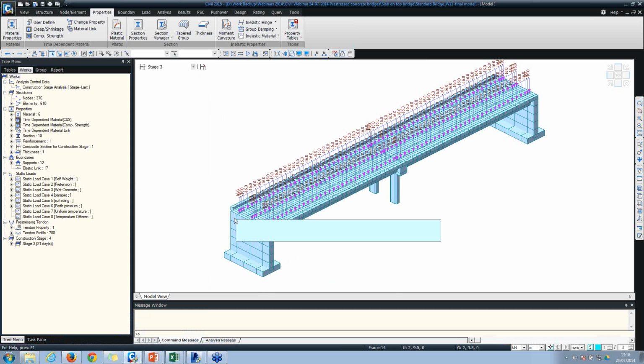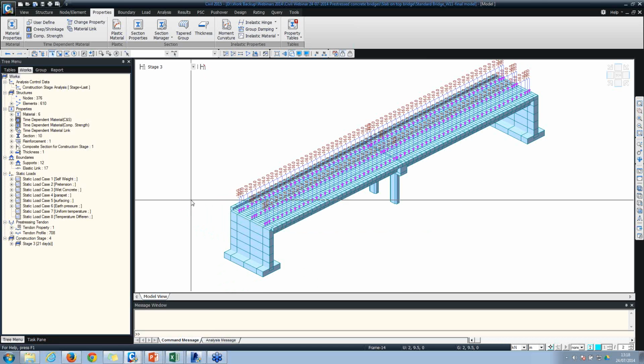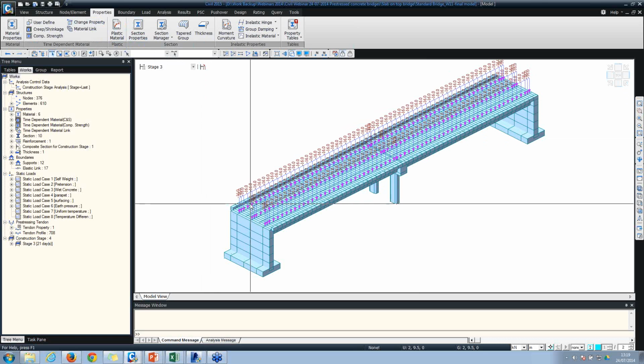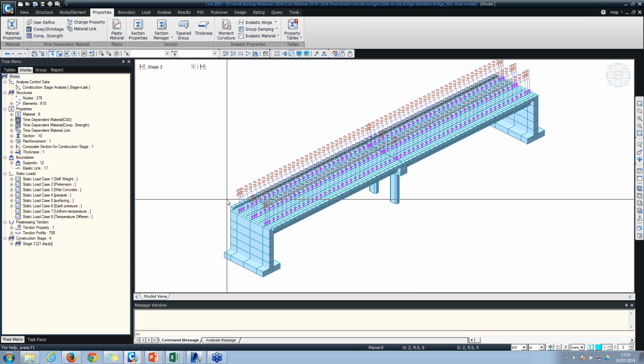Okay, so just to pause here, I've got a few questions I would like to answer. One of our attendees has asked, can the tendon template be used to edit the tendon subsequently? Yeah, as I said, you can save the tendon template input as a tendon file, export it, and then import it back and edit, and then apply it again. And another question is how the top slab is connected to PC beams. Well, because this is a composite section, it's assumed a rigid connection. But for designing purposes, we do check for the interface shear between the slab and the PC beams.